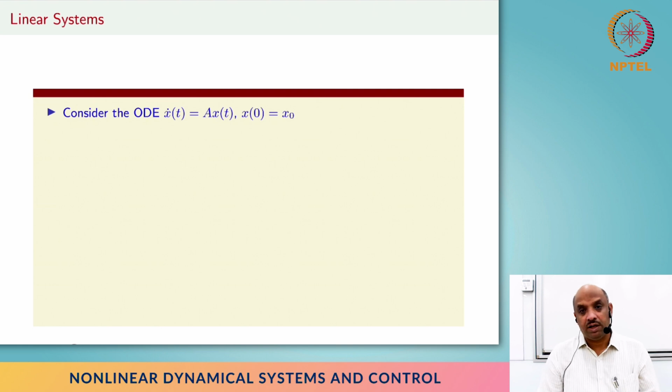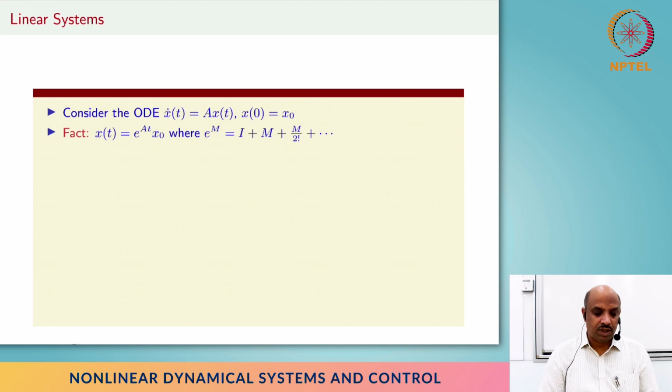So how do we connect all these things with linear systems? Can we actually apply the notions of nonlinear system behavior in the sense of Lyapunov and asymptotic stability to linear systems? Because in linear systems we typically are familiar with roots and poles and zeros and things like that. As I indicated earlier, you have transfer functions that can be transformed into state space, where you have x dot equals Ax plus Bu, and then there's an equivalence, right? So here we are just trying to understand the stability behavior from the definitions that we developed for nonlinear systems, and everything works out perfectly, right?